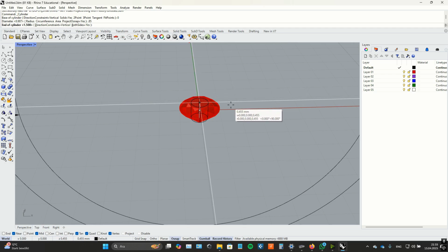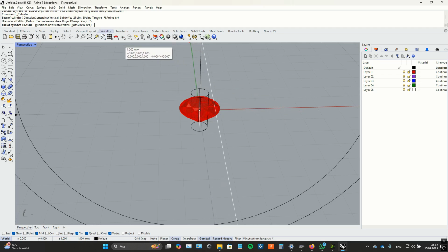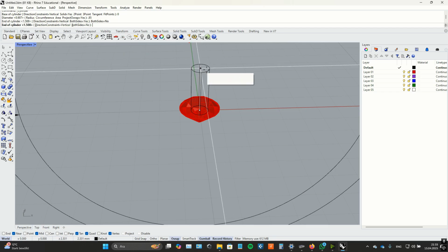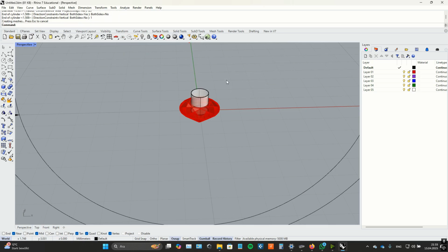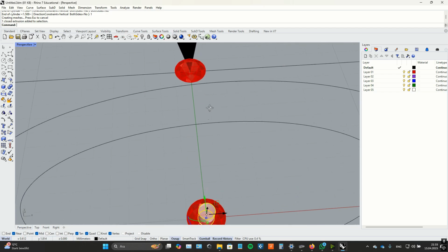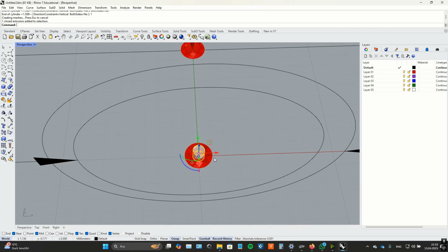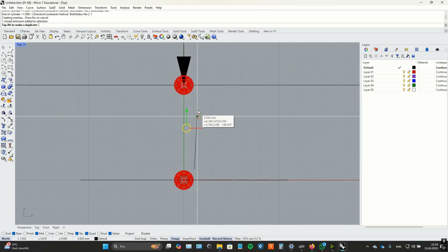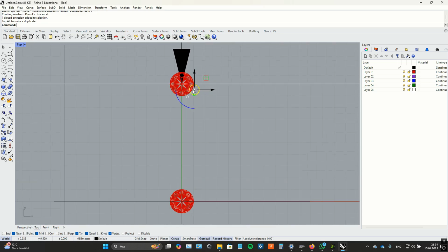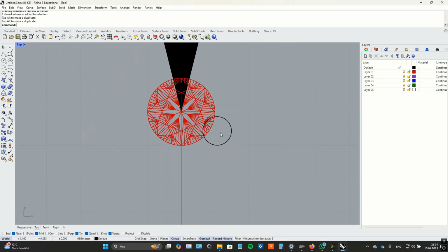So I'm just entering 1 millimeter here. Since both sides is on, it's going to make 2 millimeters, but I'm just turning this off and hit 1 and enter. So that's going to be my prong. Let's position the prong. Let's place it like this for a moment.